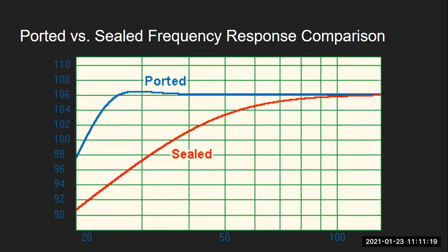You can see that port really fills in as the typical sealed configuration would be rolling off. It's not exactly what's happening, but it's a good visualization of what could be going on. But it's filling in, but it drops off much steeper. So you end up getting that lower frequency extension, but once you've reached your low corner, that's about it.